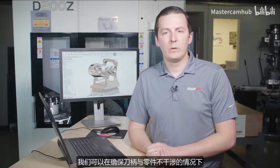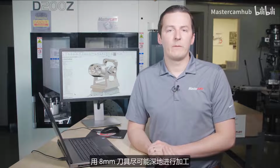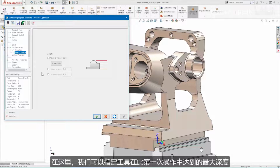With tool holder collision checking, we can be sure that the 8mm tool is reaching as deep as it possibly can, while keeping the tool holder safely away from the finished part geometry. We start with a simple OptiRough toolpath from the top plane. Here, we can specify a maximum depth for the tool to reach on this first operation.